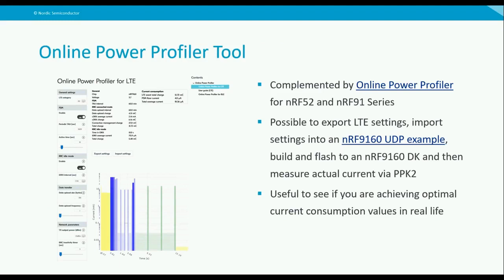The Power Profiler Kit 2 is complemented by the online Power Profiler tool. This tool is based on a model of measured values, which should give a good theoretical indication of what power consumption you can expect from Nordic hardware, supporting both nRF52 and the nRF91 series. Once you have a proof of concept, you can check values from the online Power Profiler with the PPK2 values to double check that everything is working as expected. Due to a lot of environmental factors, it's a good idea to verify these numbers for your physical device in the expected operating environment.